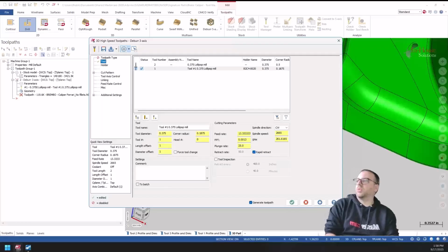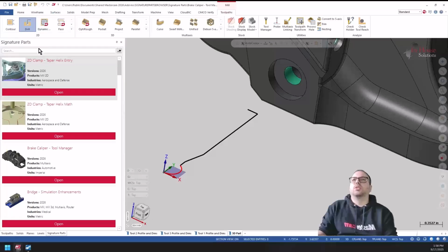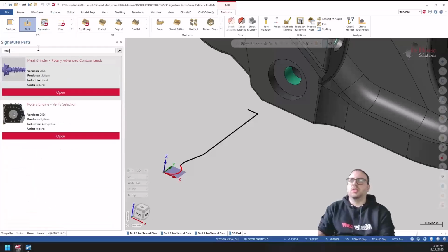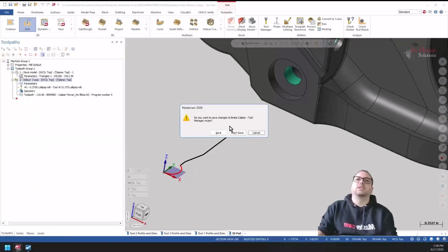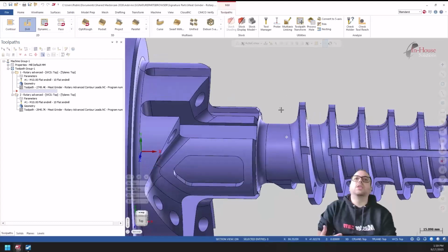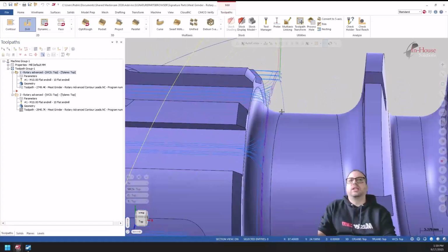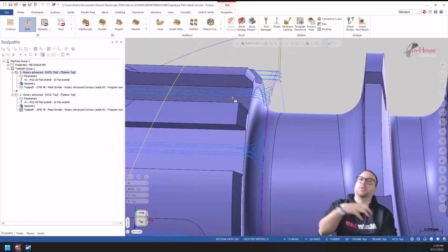Okay, we're almost done with milling. There's 3 little things with multi-axis toolpath. So first of all, there's the rotary advance. So anybody with a multi-axis license who's ever used that toolpath, it's a great toolpath. One new thing that they've introduced is the ability to create extra lead in, lead out when you're coming from the outside of your part.